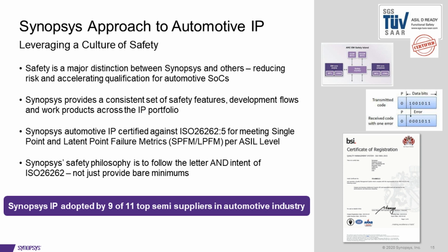So I think one of the things that's important to note, and this especially goes to the concept of systematic safety, is that it's not simple enough to just say, okay, I've put a couple of blocks onto my SoC. They each have a checkbox that they're ASIL B or ASIL D compliant, and so now I have an ASIL D compliant SoC. It's not that simple. It's a much more comprehensive type of requirements around a safety certification.